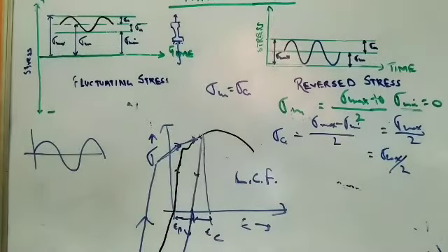This normally takes place in a nuclear reactor, when through the pipes you pass hot water and in the next moment you pass cold water through it. So the pipe expands due to thermal expansion. It expands beyond the yield stress, and when it contracts, it comes down below its normal position. So it is a tension compression. So this is called a low cycle fatigue, or a high strain fatigue. Now if you see, these conditions are very dangerous. Why these conditions?